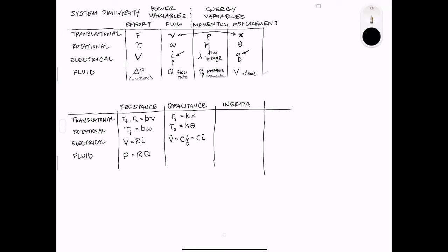This is not I dot, this is just I. And then the equation that we've been using is I equals C times dV over dt. And then we recast this value right here into just C. And that's why we've been using that component relationship, since it's a little bit easier to extract out the state variables, but it all starts from that original capacitive equation, V equals 1 over C times Q. And it's even easier if we actually take the constant and invert it right here. So 1 over C, 1 over C, and then this one becomes a C. Hopefully it wasn't too messy.